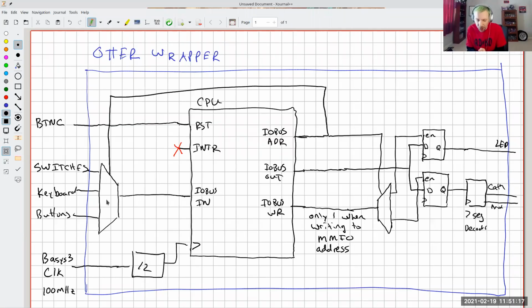Going back, we were talking about the memory mapped IO addresses. Since you're building this mux, you get to make this select go to whatever you want. The only stipulation is that the address you pick should be a multiple of 4. Why? In fact, it has to be a multiple of 4, because it would have to be compatible with the save word instruction.